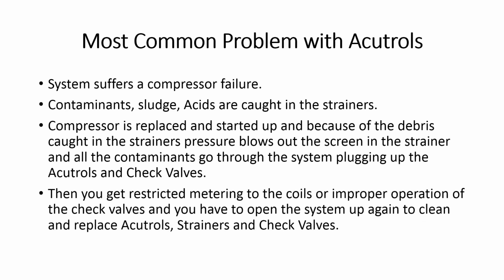Then you get restricted metering to the coils or improper operation of the check valves, and you have to open the system up again to clean and replace Accutrols, strainers, and check valves.